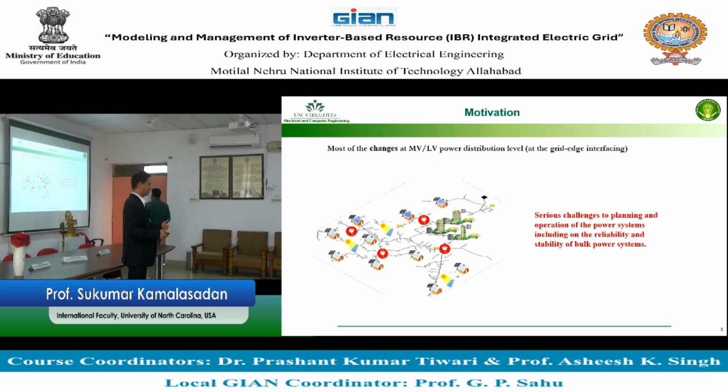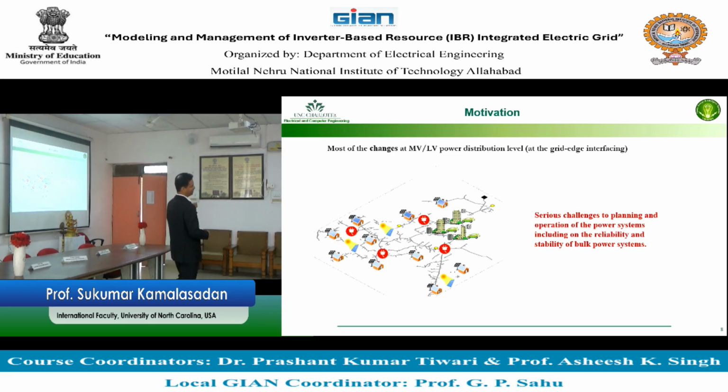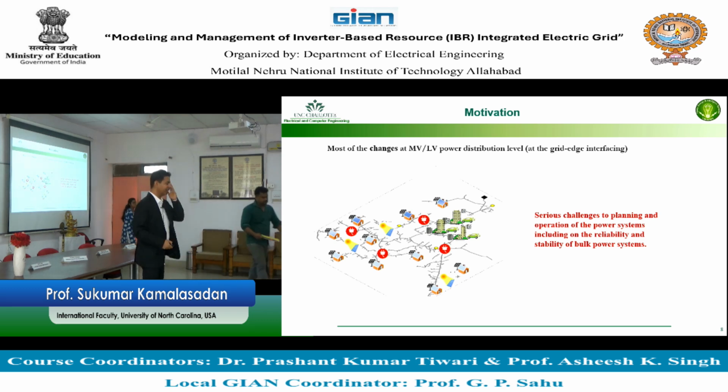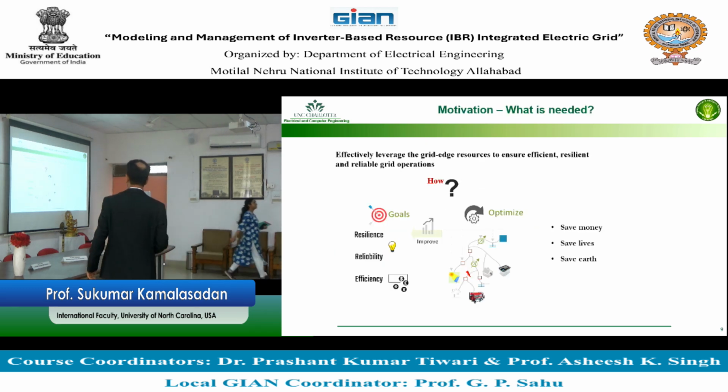Voltage will go up because you're pushing power into it. So is that photovoltaic on the rooftop at the edge of the electric grid a blessing? Yes, it could be a blessing for voltage. However, what happens if this photovoltaic is producing high and producing low, high and low? It will become very problematic with respect to the voltage. So grid edge management is also critical.